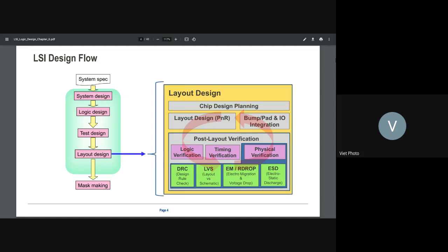Middle 2 and middle 3 need to be connected. That connection is realized by the via. Between middle 1 and middle 2, that's via 1. So the via number is always taken after the lower layers. Middle 2 to middle 1 is via 1. Middle 5 to middle 6 is via 6. That's kind of a convention, right? So the convention is so that you can see that.